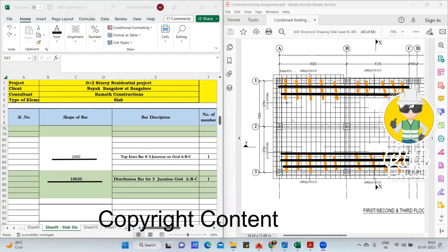this part. Okay. So this is a continuous slab. Continuous. Finish. You know already how it has to be done. I won't explain it again. Okay. This distribution I'll find now. On this side, it will be plus 1. If I do it here, it will be plus 2. So when I find the number of bars, it has to be plus 2.